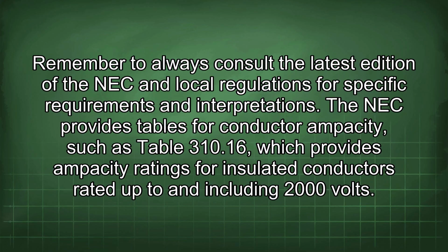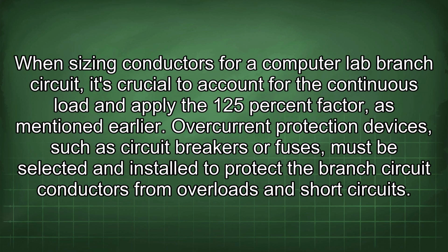The NEC provides tables for conductor ampacity, such as Table 310.16, which provides ampacity ratings for insulated conductors rated up to and including 2000 volts. When sizing conductors for a computer lab branch circuit, it's crucial to account for the continuous load and apply the 125% factor, as mentioned earlier.